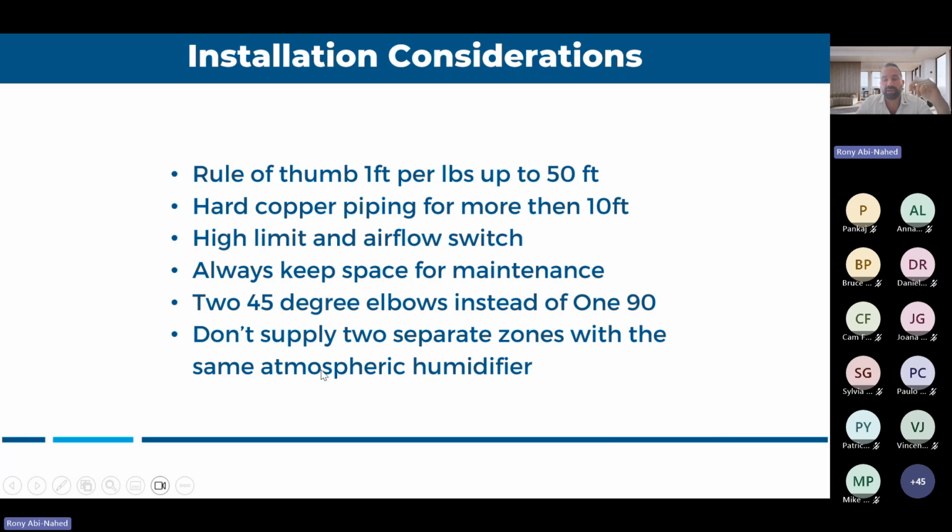So let's say you have 1 generator, 2 separate grids and 2 separate ducts. Whichever duct is asking for more humidity, or has the conditions to get more humidity, that's where the humidity will go. So you can't control your set point when you split 2 different zones with 1 unit. So you always need 1 unit per zone.